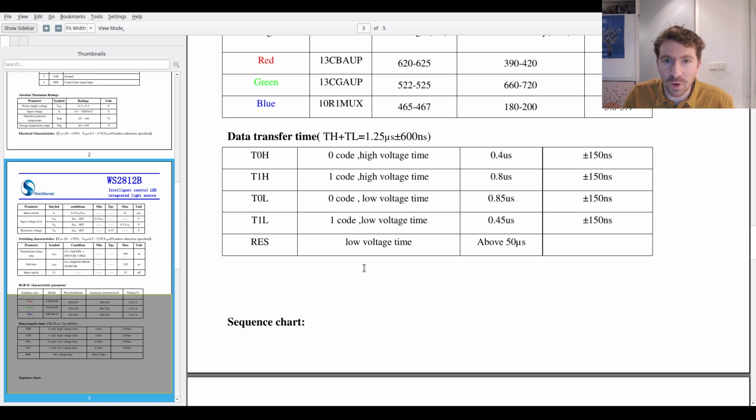I'm sorry, I was just thinking that I have an error in my drawing, because I said plus minus 300 nanoseconds, and they put plus minus 600 nanoseconds here. That doesn't really work out if you think about it, because this would be minus 150 nanoseconds, this is plus. That's kind of your worst point. That's a 300 nanosecond span, so I don't know where this number 600 nanoseconds comes from, but okay, keep it in mind.